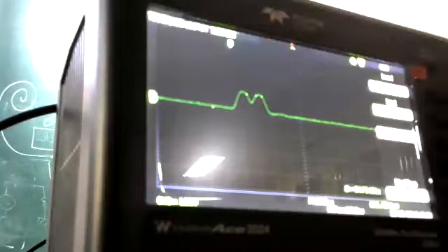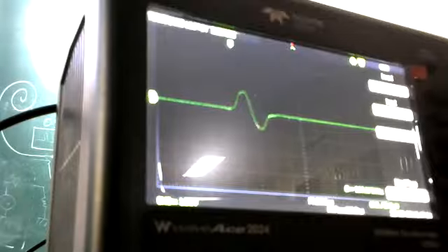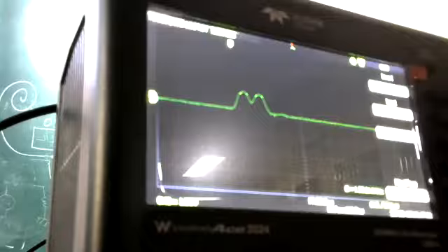Let's come back again. We will try one more boundary condition, which is a short circuit. So I'm just taking a piece of metal and shorting the center pin to the ground. Oops. Oh, come on. So you see that the sign flips, right? Obviously, this is not a very good short circuit, but it does a fairly decent job at low frequencies.